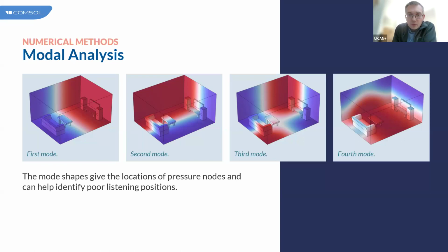Another question from an anonymous attendee. I don't know whether we've got time for this, but you decide, Robbie. Can you briefly explain why DGFEM requires low computational cost compared to conventional FEM? So the reason is that conventional FEM will generate a system matrix, or stiffness matrix if you prefer. And the costly part of solving something using the finite element method is actually inverting this large stiffness matrix.